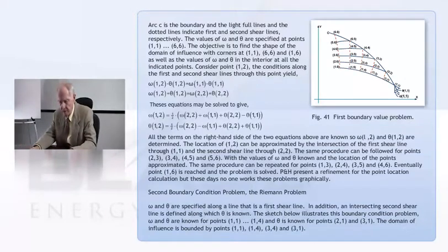And what I have is a characteristic result for a hyperbolic equation. That is, given the information on the heavy solid line, I know everything within the domain of influence. And that's the little triangular looking figure there. Not that I couldn't have gone outside, but supposing that the heavy line is on a boundary, so I'm not really caring about anything with a slip line field outside. So this domain of influence is all that I can get, but I can get everything just starting with a line. And that's the Cauchy problem.